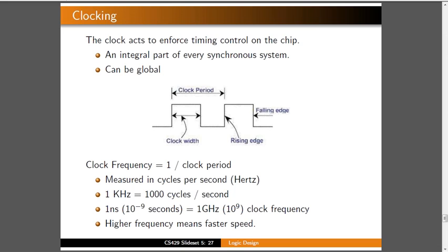For example, suppose A and B are not synchronized with each other. A wants to send 5 bits to B. So A adds one extra bit, 0, at the beginning, and inserts a 1 at the end. So A adds 2 extra bits. Whenever there is a 5-bit or 6-bit register, 2 more bits are added. If 5, then 2 extra bits, that is 7. If 7, 2 extra bits, that is 9. If 6, 2 extra bits, that is 8.